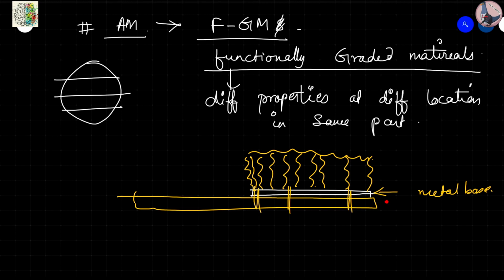So this is wood, this is metal, and this is some porous material. Such combinations can be possible while making with 3D printing. Wood you cannot manufacture, but it is just being fastened, so there is no trouble. For a while you can use some metal powders to make this base, and then you can change your material and use a different material to make this part of it.